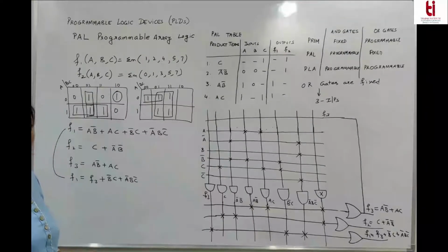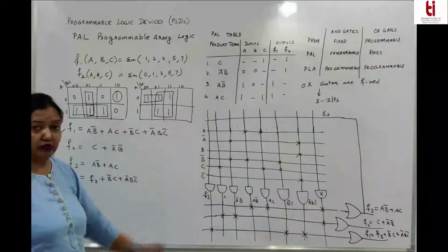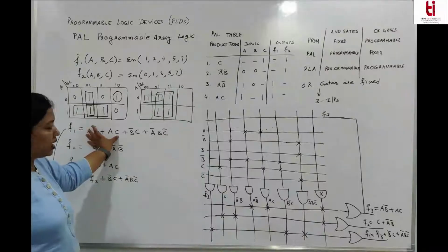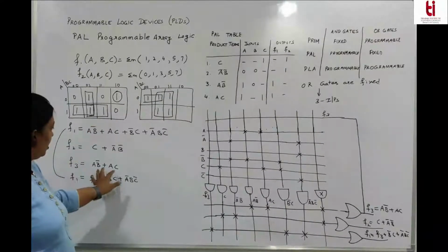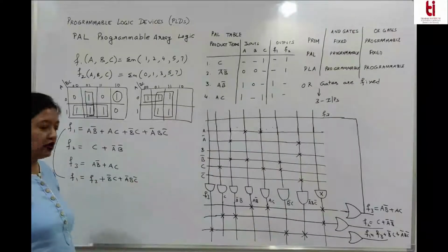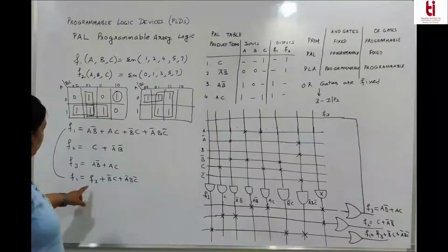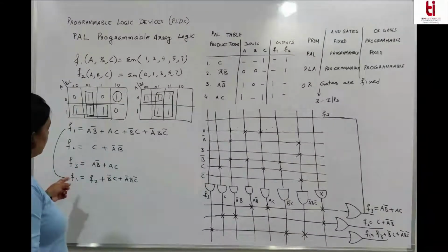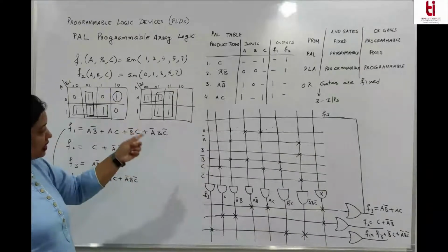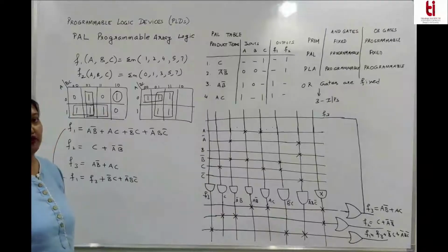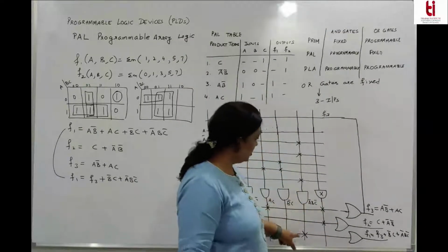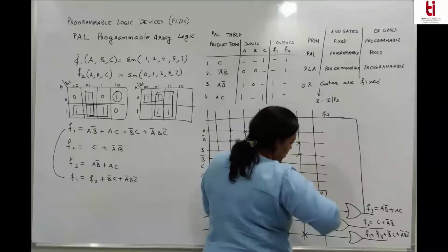If the product terms are less, then they can be easily implemented by making one of the inputs 0 for an OR gate. But if they are more, then how to implement that using an OR gate? What you do is, you use a part of this expression as a third output. So your function becomes sum of 3 product terms, F3, this and this. So when you have this, you can generate F3, which is a sum of 2 product terms, and you can simply take that output as an input, and you can get the F1 and F2. So here again this gate has 3 product terms as the inputs. So one of the product terms will be 0. This AND gate is actually generating 0.